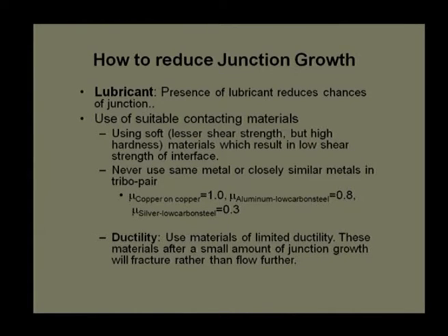Sometimes we play with the ductility also. We use a low ductile material which can be easily ruptured. Apply a slight force on that, it can be easily ruptured at the interface, and that will provide a low coefficient of friction. However, there is a problem. If that rupture happens to be very rapid, or it deteriorates the surface softness, then we should not use this kind of suggestion. We should use some sort of lubricant, or many times we use water to lubricate the surfaces.